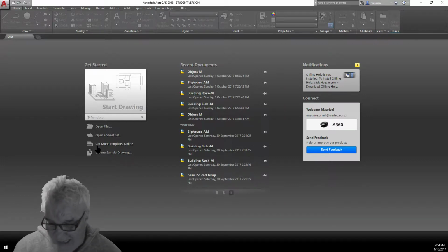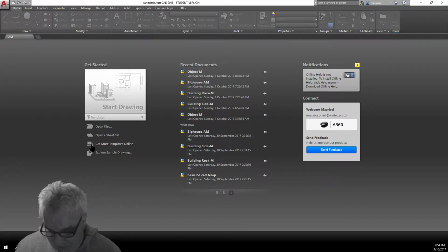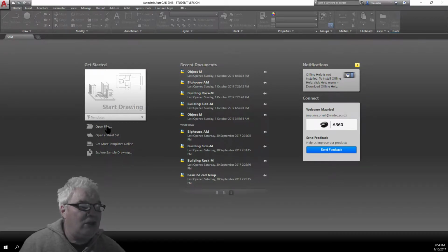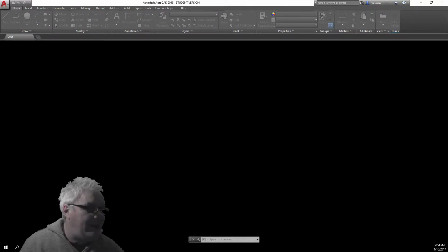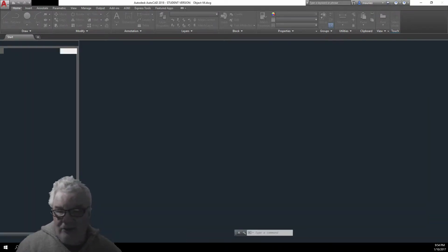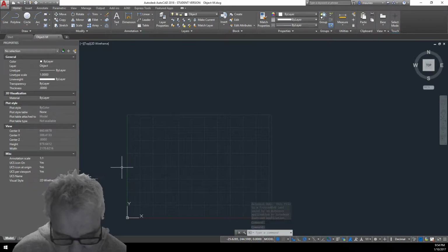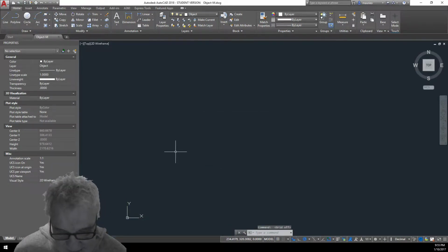We're on practice number 2, and the first task is to draw lines with dynamic input. We've got some lines there to draw. I'm just going to move the little book. It's asking us to open a blank file called Object M, which is there, and that opens up as a file. It says if the grid lines are displayed, click them off. They just toggle on and off. They're on because they're blue, and we click them off like that. That's step 1.